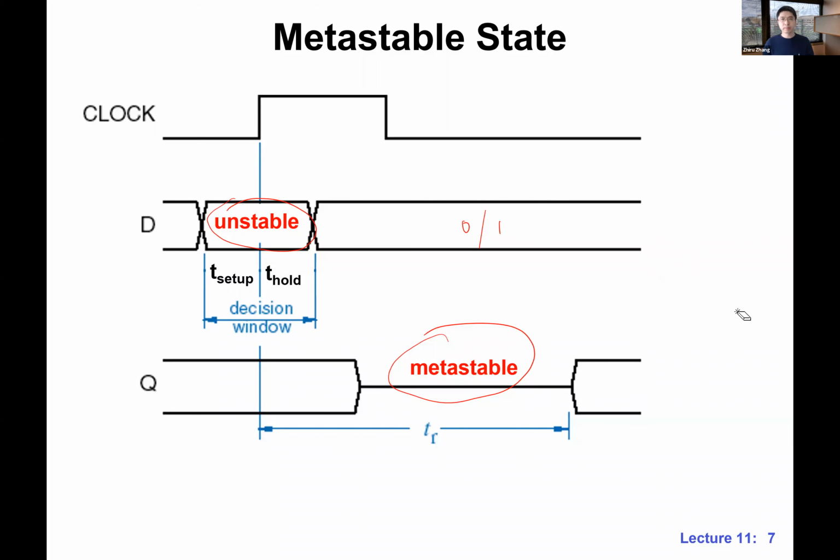So we basically have a slower, longer path here, and a faster path at the bottom. Since this path is lagging behind for a moment, this is what causes this gap, which eventually leads to this dip, this glitch. In other words, it's already summarized here: these glitches are typically caused by unequal signal propagation delays in the circuit. Make sense? Any question about this one?